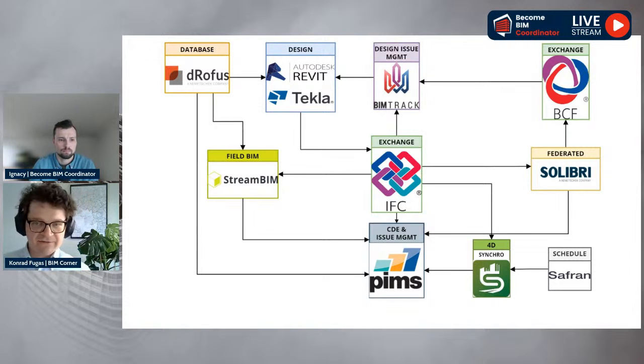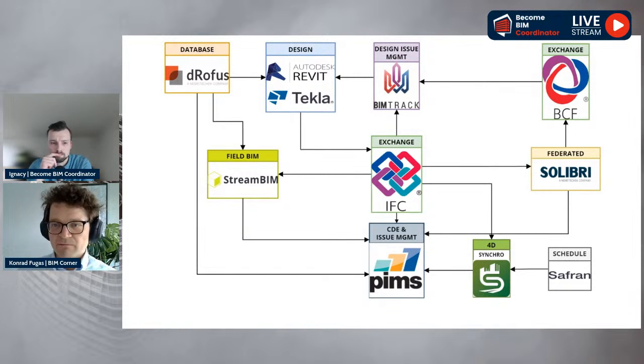Schedules are made in Safran Project, and are also combined with data in PIMS into single activities in web registered, available for site managers and foremen. We combine IFC models with schedules in Synchro for schedule visualizations, so-called 4D BIM.